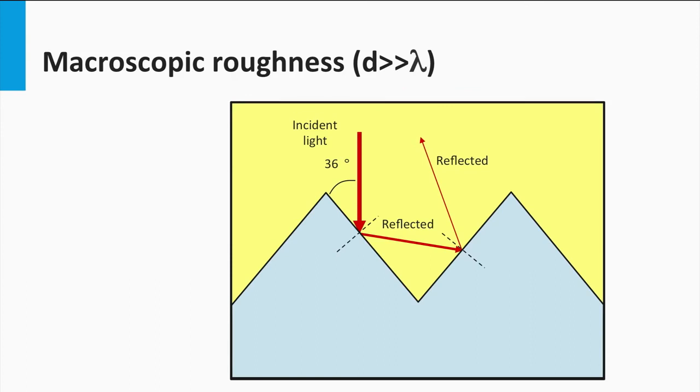As discussed last week, texturing of the surface can improve the light incoupling as well. Light that is reflected at the textured surface can be reflected at angles in which the trajectory of the light ray is incident somewhere else on the surface. Here the light can still be coupled into the silicon. Secondly, the scattering at textured surfaces will couple the light under angles into the wafer. This means that the absorption path length will be enhanced. This certainly enhances the absorption of the light with a wavelength above 900 nanometers.